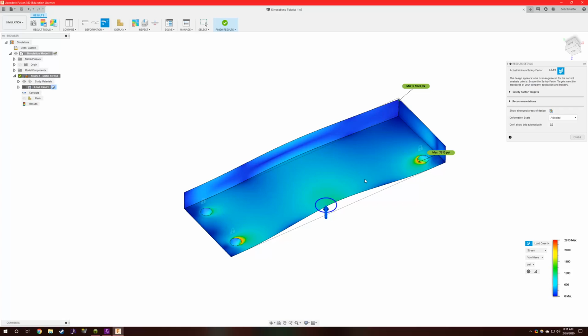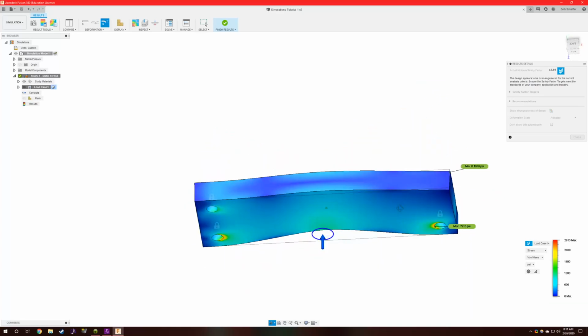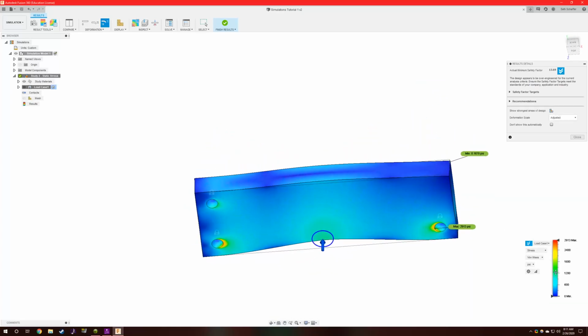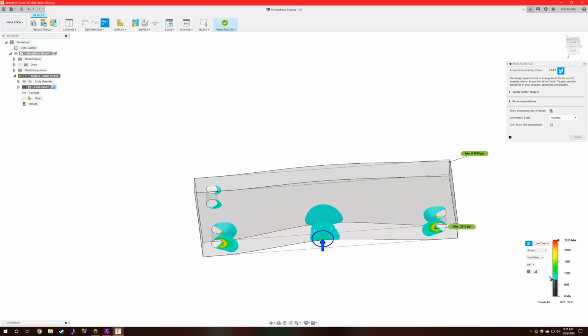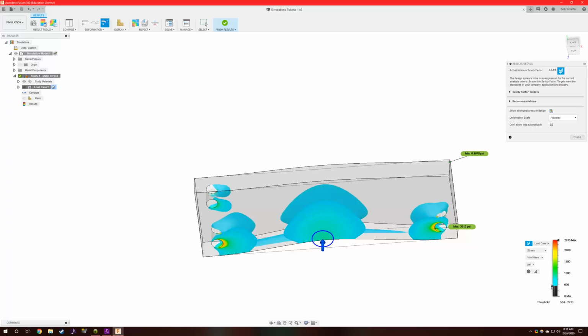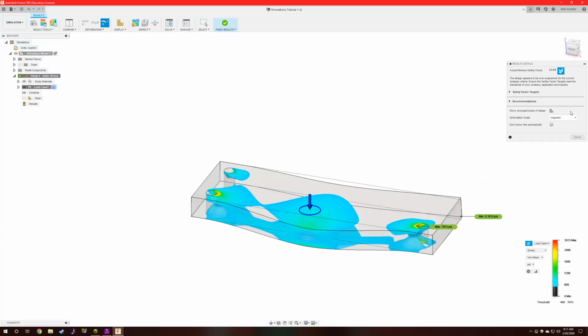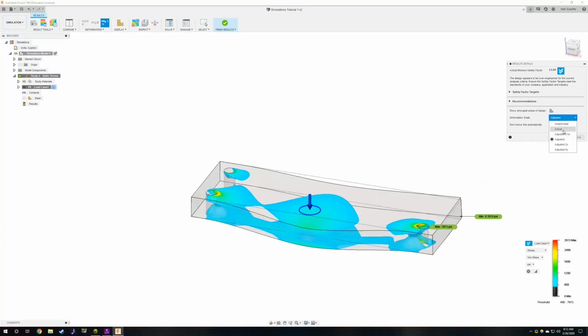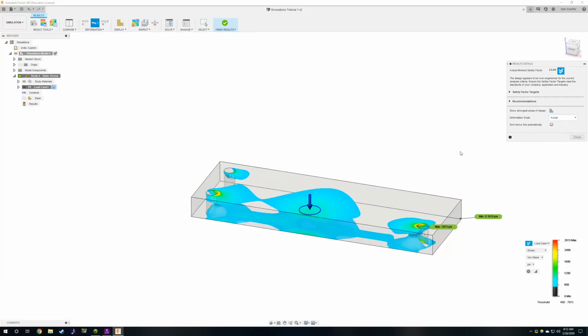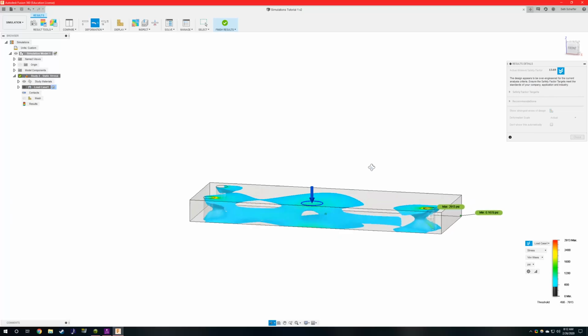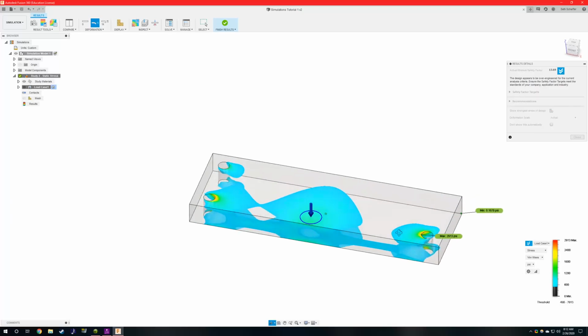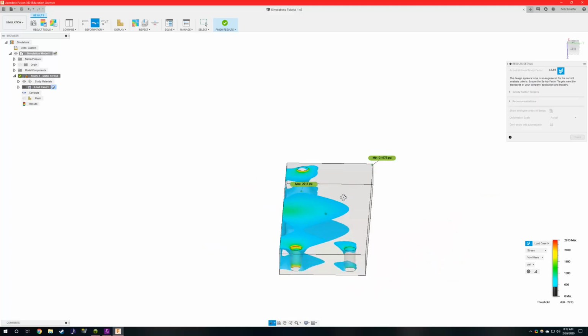So there are two ways to do that. Number one, you can just look at it and see what areas are red and yellow and green and whatnot. Number two, more helpfully, is we drag these sliders. We can actually zero in on the areas of the highest stress. So as we decrease this, you'll see that the load tends to be carried on, unsurprisingly, places in between where the different connections are. So if I switch this back to actual just so that we can see it in a straight line, you can see that the load tends to be carried along this bottom edge and these faces.